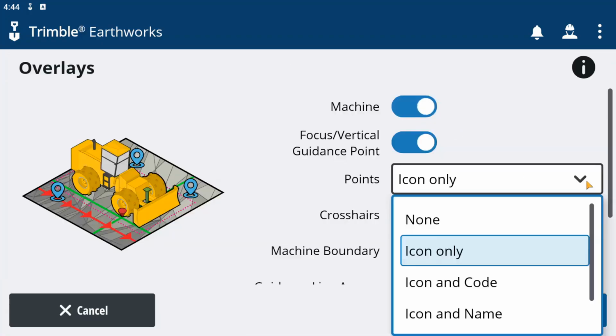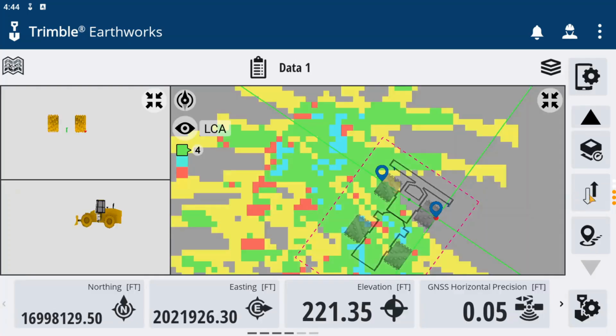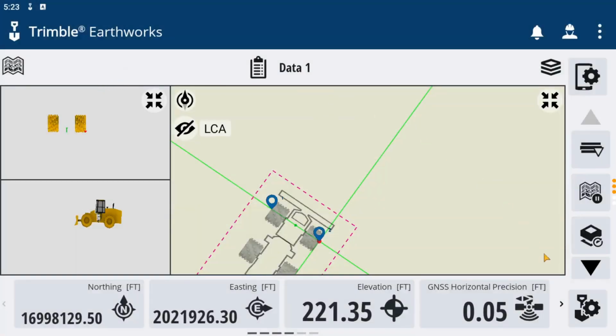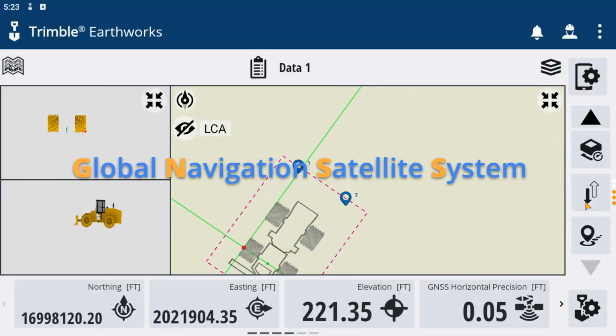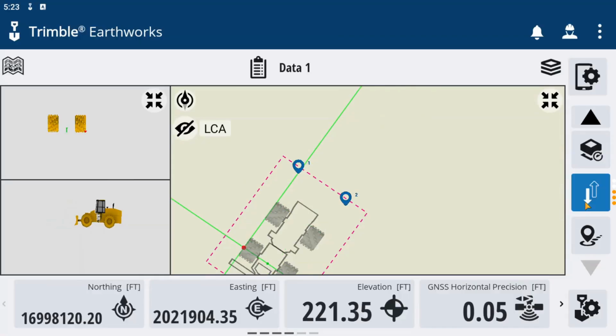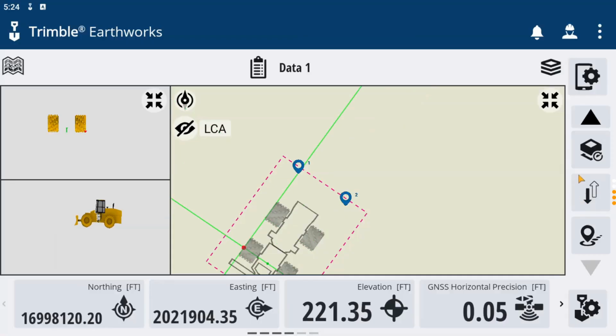Due to having a single GNSS configuration, the machine will not know its heading until moving. Press here to indicate travel direction. Due to most landfill compactors being single GNSS configurations, you will need to tell the system which direction you are facing. Dual GNSS systems such as landfill dozers do not require this step, as having two GNSS receivers allows the system to calculate its heading.